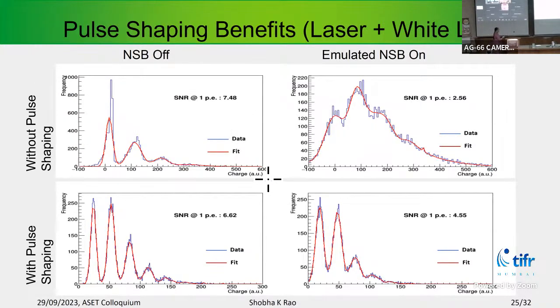So why does it suddenly become flat? In case of any nonlinearity, it should be gradual. No, because our electronics is not soft saturation. It goes into rail saturation. Buffers and all that. So we have adjusted.